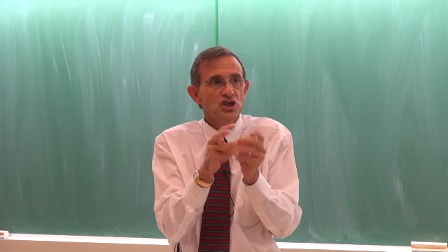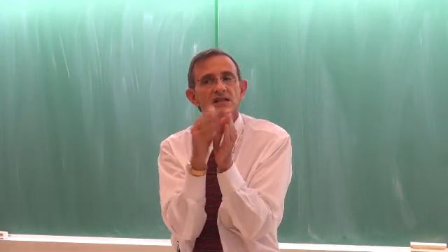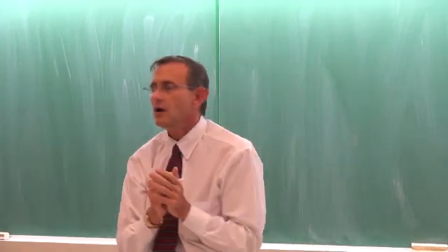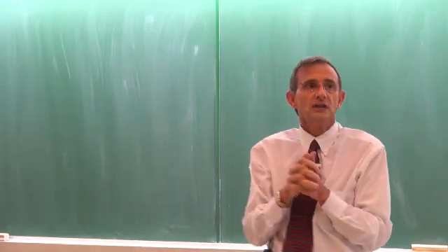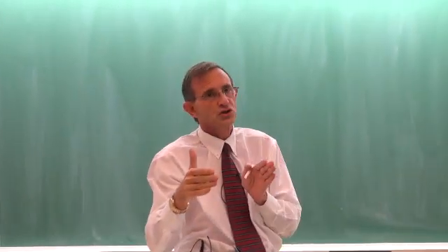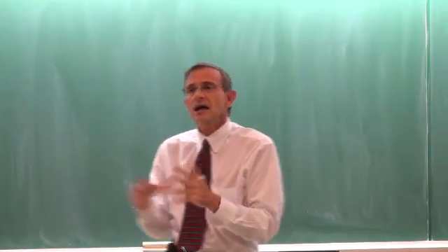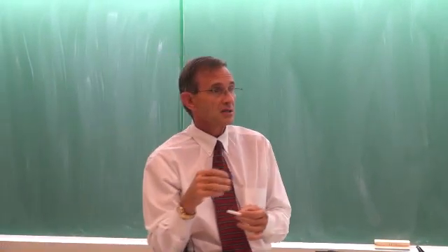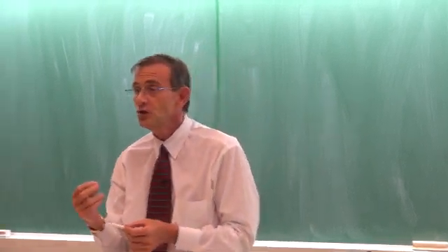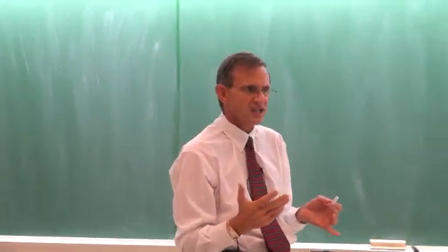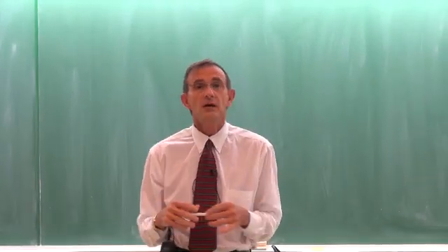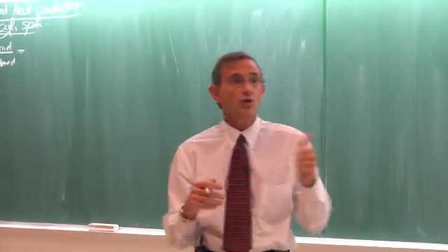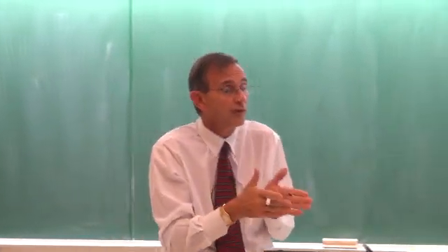So the temperature distribution, non-dimensionalized, is a sum of an infinite number of terms. Fortunately, we have seen that the second and the third term decay very, very quickly. And it has been found through experimentation that if tau, the non-dimensionalized time, is larger than 0.2, then the result will be within 2%, which is quite reasonable. And for that case, you only need to use one term, the first term.